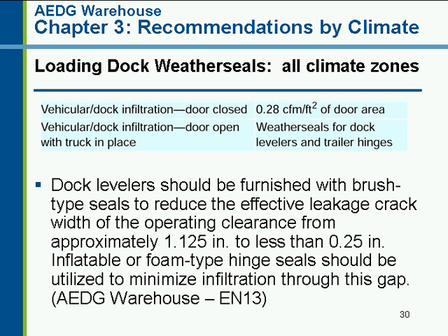In addition to those general requirements, which apply across much of the guides with some slight variations in insulation R value, some of the guides have specific requirements for particular building types. For example, the warehouse guide has a requirement for loading dock weather seals, and this applies for all climate zones. And it sets maximum infiltration levels both with doors open and how you address infiltration when the door is closed. So when it's closed, you want the maximum leakage to be 0.28 cubic feet per minute per square foot of door area.